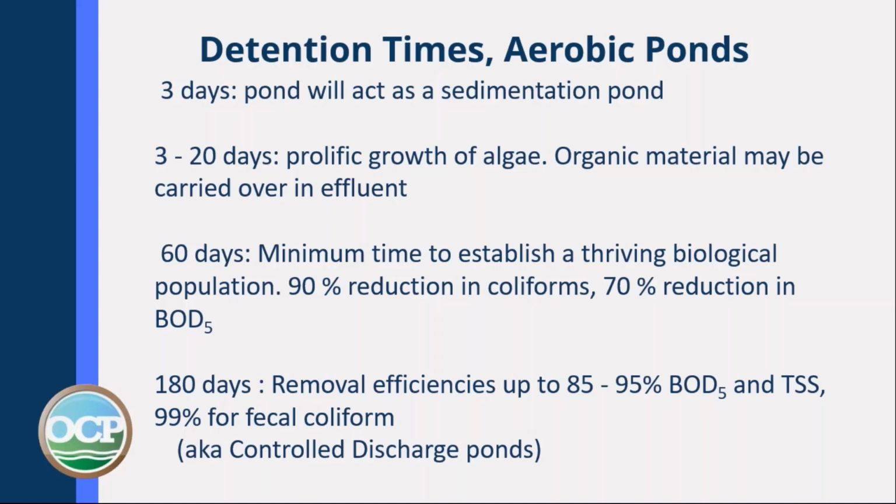And if you have 180 days detention, you can get removal efficiencies of up to 85 to 95% for BOD5 and TSS, and up to 99% for fecal coliform using controlled discharge ponds.